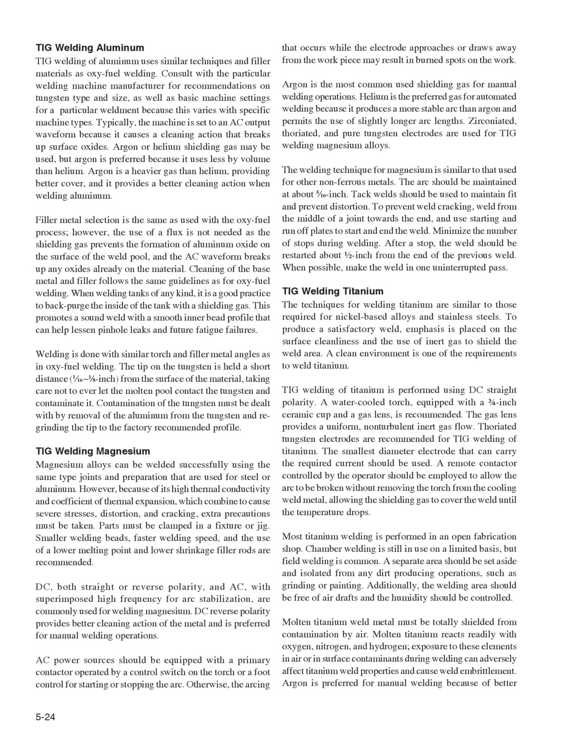Typically, the machine is set to an AC output waveform because it causes a cleaning action that breaks up surface oxides. Argon or helium shielding gas may be used, but argon is preferred because it uses less by volume than helium. Argon is a heavier gas than helium, providing better cover, and it provides a better cleaning action when welding aluminum. Filler metal selection is the same as used with the oxy-fuel process, however, the use of a flux is not needed as the shielding gas prevents the formation of aluminum oxide on the surface of the weld pool, and the AC waveform breaks up any oxides already on the material.